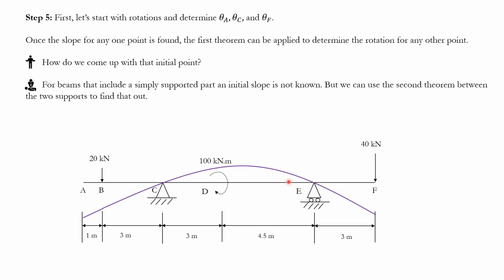And for us in this case, we actually need theta C anyways, right? So I'm going to draw TE with respect to C. I'm going to draw the tangent from C and stop at E. This is TE with respect to C. Why? Because again, the deviation is drawn from E, the tangent is drawn from C. Okay? And so I got TE with respect to C.